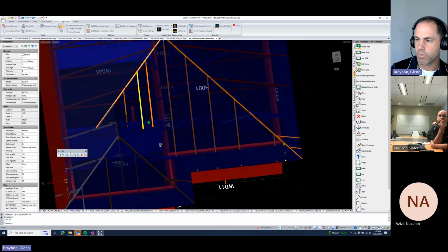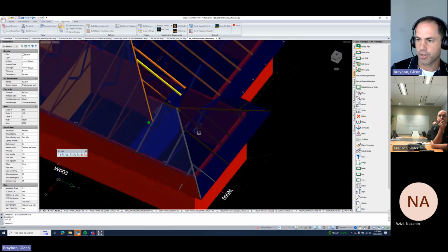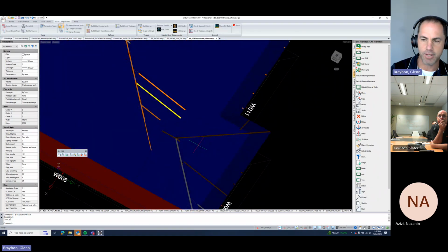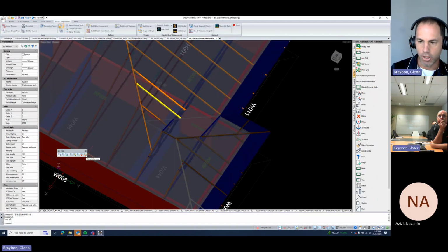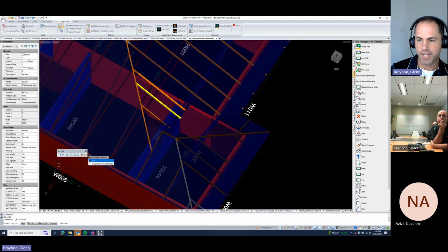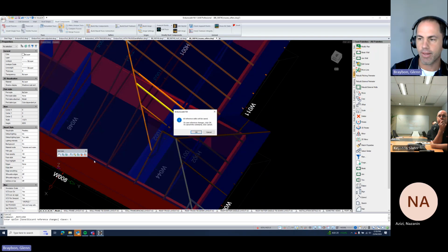So you can see the screen's a bit darker than before because we're editing the block reference in place. Then you close out of the reference and you save changes. When I press this button, we're going to lose all those changes because there is a bug in there at the moment, but you would hit save and then all reference edits will be saved.